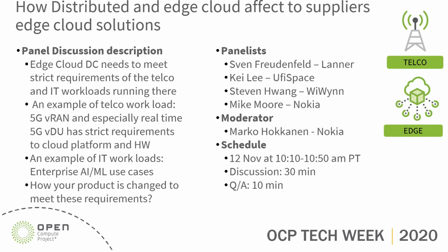So we see an opportunity to make this a lot more effective by turning an RU tied to the antenna into one talking to a pool of BBUs, by virtualizing the BBU function. That is something we are working on by developing the fronthaul gateway and also the converged access switch.